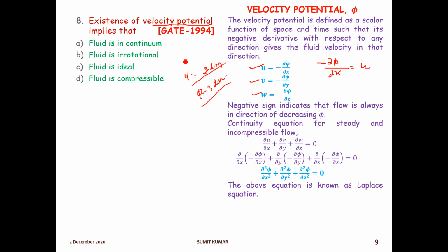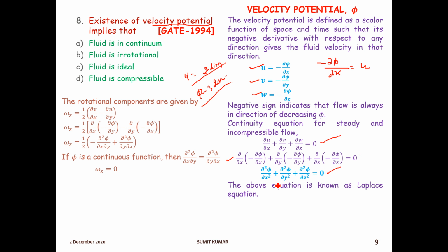So here we can see if this is the equation of continuity for incompressible flow. If we replace this u with this phi function, it will become this one, and finally this, and this equation is known as the Laplace equation. Okay, so this is the Laplace equation.